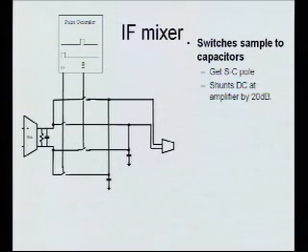But rather than spending the power to amplify and filter some more, I'd like to just go down to baseband, because once I'm at baseband, filtering is much easier. I just make a low-pass filter at the band with my information and suppress everything. But we know mixers mix down things besides the wanted frequency. They mix down the third harmonic, the fifth harmonic. This is all differential, so that's true. All the odd harmonics come down.